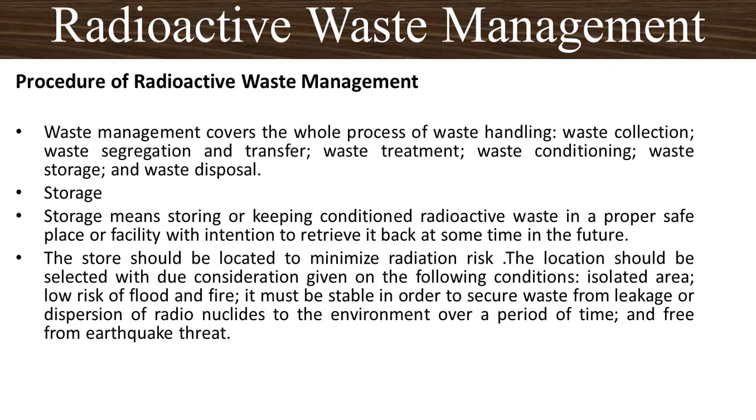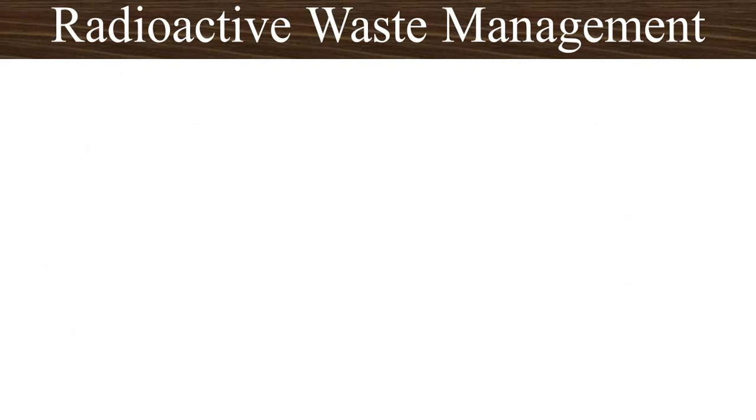The next one, storage. Storage means storing or keeping conditioned radioactive waste in a proper safe place or facility with the intention to retrieve it back at some time in the future. The store should be located to minimize radiation risk. The location should be selected with due consideration given on the following conditions. It should be isolated area, low risk of flood and fire. It must be stable in order to secure waste from leakage or dispersion of radionuclides to the environment over a period of time, free from earthquake threat.